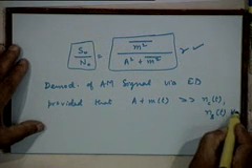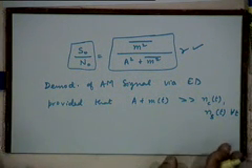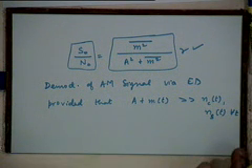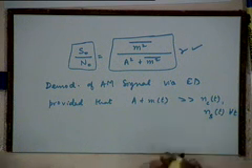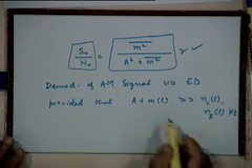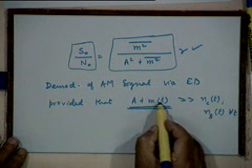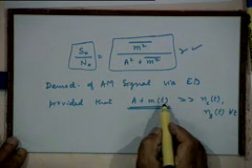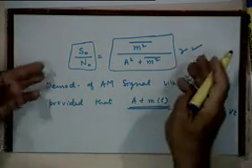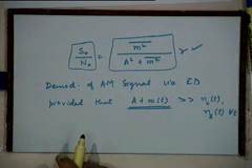That is, if for all time or most of the time the noise remains much smaller than the signal amplitude, by signal here I do not mean just the signal, but carrier plus signal, then we get the same expression for the output SNR. So, there is no difference in the performance of a synchronous demodulator or an envelope detector under small noise conditions.